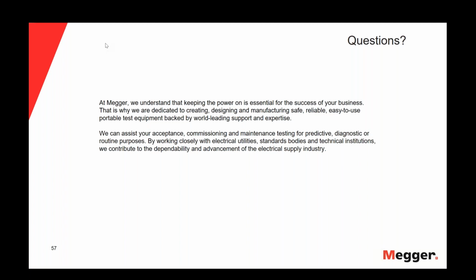Typically, you are in the giga or tera ohms on a good cable, and the PILC cables are a little lower. Typically, a good paper cable might be in the range of maybe 50 megohms. So it is a little lower, but the solid dielectric cables are really very, very high in their insulation resistance.